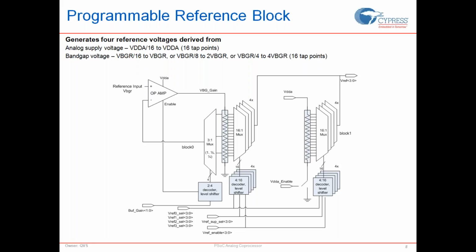Also, if you think about this, each of these reference options is kind of like a VDAC for you. The only thing you need to understand is that all of these outputs are coming out of a resistor array or a tap on a resistor, which means their outputs are not low output impedance. That means anything that consumes it needs to be aware of it.